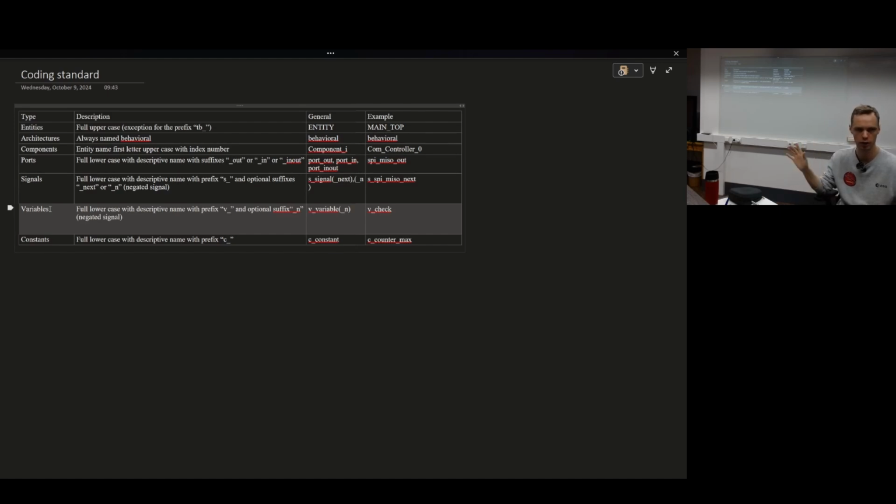I might cover it at some point shortly, but there are use cases for this, and if you code the right way with them, then it's fine. But for simplicity, we're going to leave that out, because otherwise you're going to get confused about when signals are being assigned, because variables and signals work differently when the value is being taken. And of course this will confuse, because you cannot immediately see that, especially in simulation. That's something I did in my bachelor's thesis. I mixed this up, and then you have a mess. So don't do this in the beginning. I can really tell you.